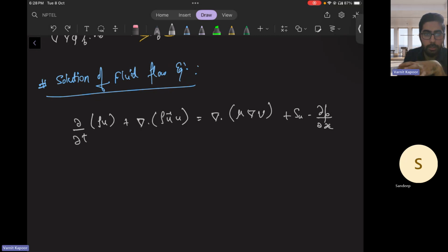Okay, so every component, every kind of discretization, we have seen how to solve the diffusion part, convection part, and steady part. So in principle, we can now solve for the convection diffusion equation or a general scalar transport equation for the scalar phi or u. So if you look at the fluid flow equation, we basically have a similar kind of structure. The only thing is that instead of phi, there comes a u and v. So instead of one equation, we will be having two equations.